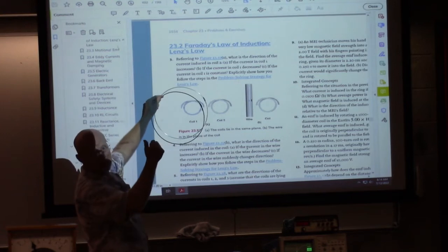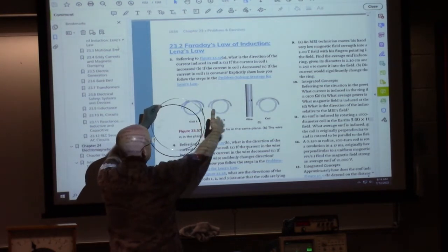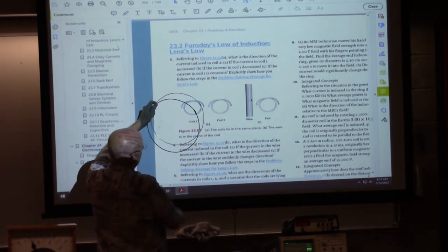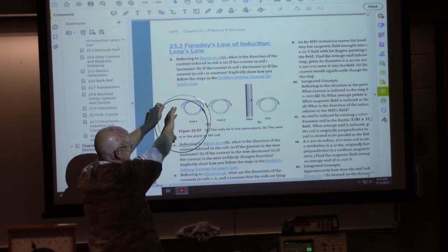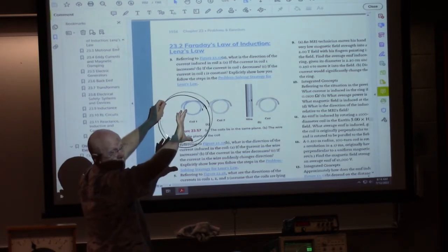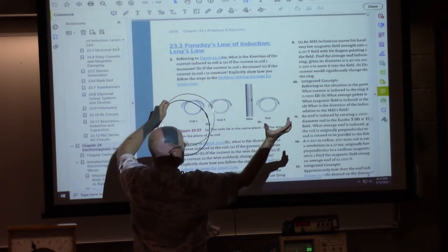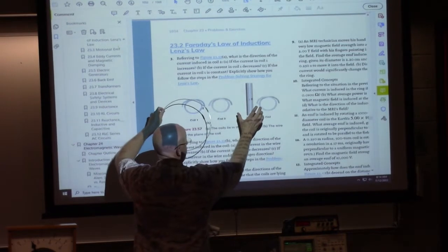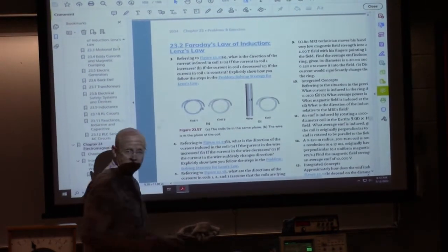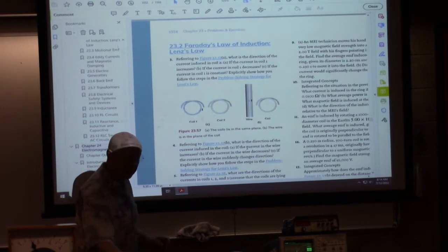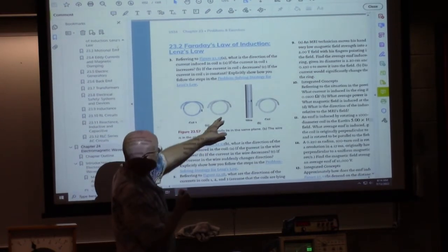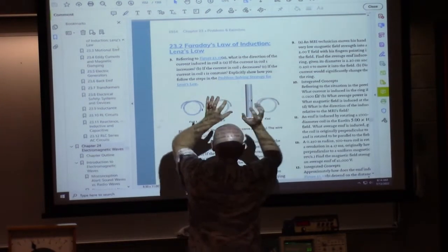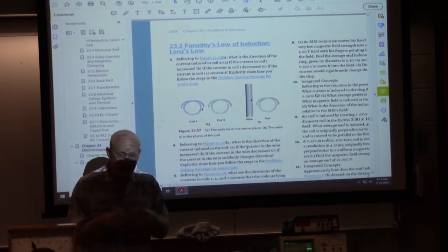And again, if you remember from right-hand rule number 2, holding the ring with your thumb in the direction of the current, we would get magnetic flux coming out of the ring, looping around, and in this case going through coil number 2 and coming in behind it. And so what's important here is to say that the flux in coil number 2, which is coming from number 1, is going in. So we have flux in.